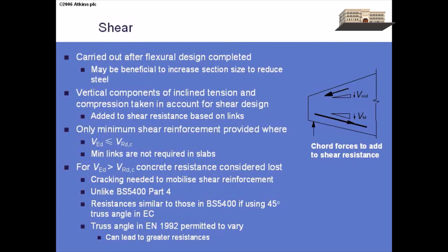In the same way as BS 5400 shear design was carried out, you'd normally have done the flexural design first and had all the cross-section and dimensions sorted out before you did the shear design. When you do the shear design, you're effectively just checking against shear and providing shear reinforcement. The same is really assumed in the Eurocode.